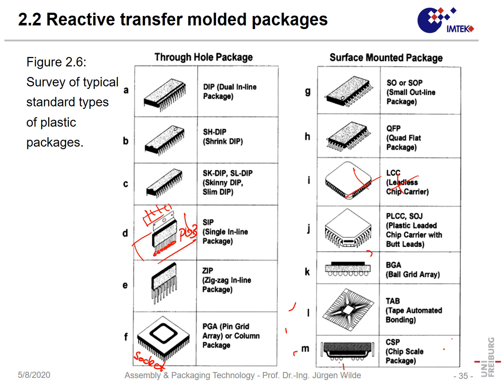What is important now is more the BGA and the chip scale package, which can be a small BGA or which is a small package which is similar to a BGA. In that way, we can see not everything was new in the first level packaging, but many surface-mounted devices were just modifications which were drawn from through-hole packages.